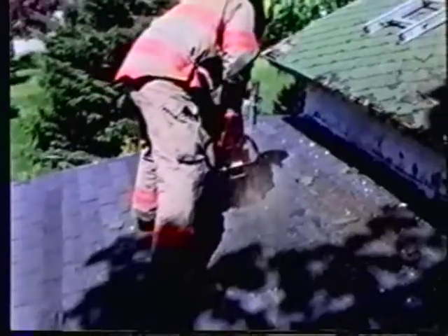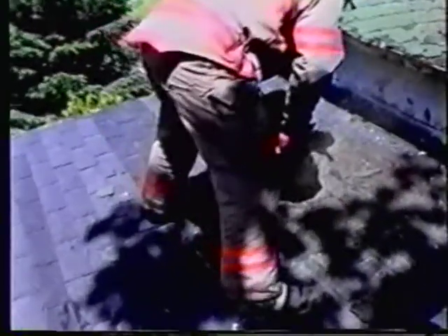First, make a horizontal cut as close to the ridge line as possible and spanning as many bays as practical. A horizontal 4-foot cut will cover a minimum of 3 bays on a 16-inch on-center rafter system. Care should be taken not to cut through the rafters. Our intention is only to remove the decking.